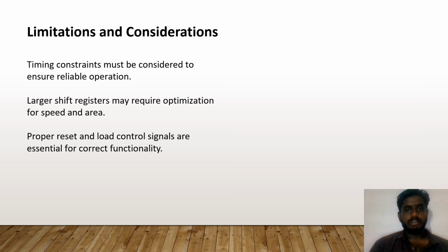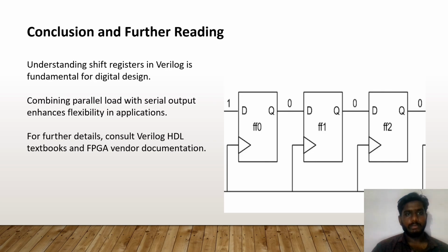Limitations and considerations. Timing constraints must be considered to ensure reliable operation. Larger shift registers may require optimization for speed and area. Proper reset and load control signals are essential for correct functionality.